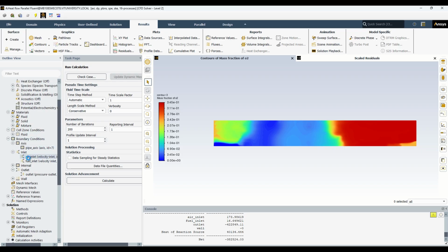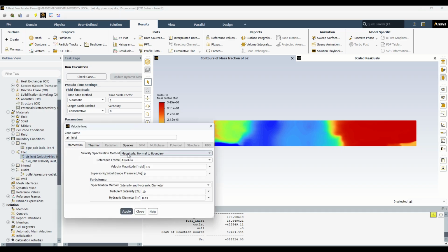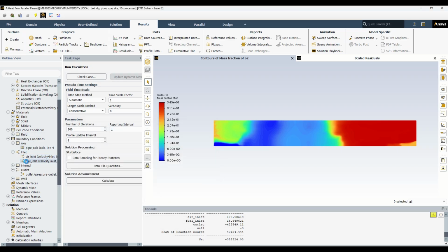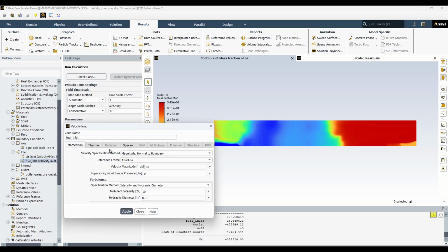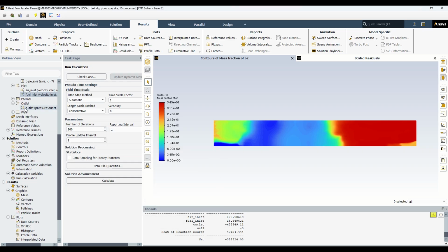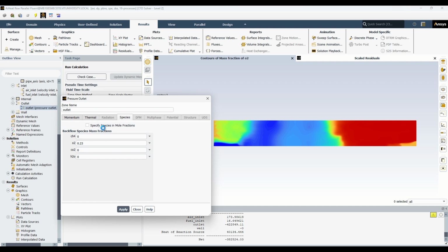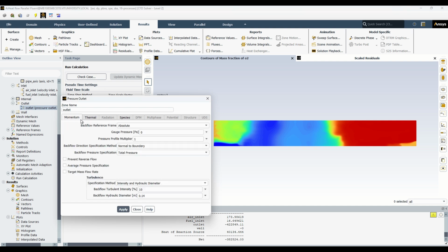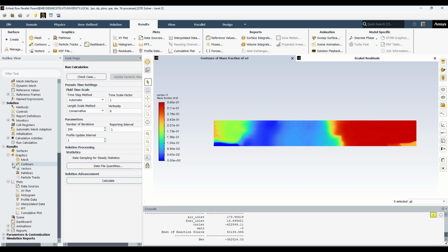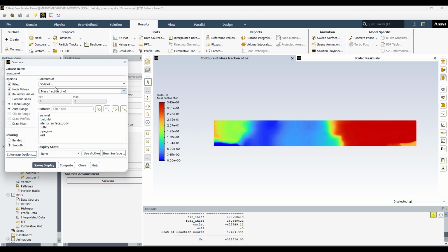We are giving air as 0.23. So the oxygen presence is very high. You can see the boundary conditions. I'm showing for the fuel inlet as well. A velocity of 80 meters per second. So methane has a mole fraction of 1. So these are the contours for mass fraction of oxygen and methane, as well as the temperature contour and then pressure contour. And we have calculated the sensible heat transfer, at the bottom you can see. So we have done the experiment successfully.